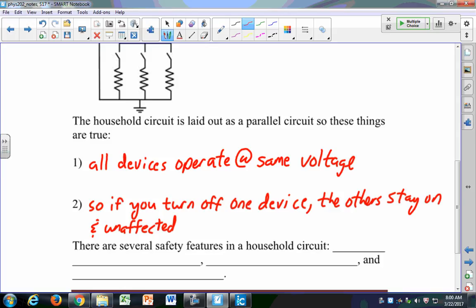It's sort of hard to think about why these are in parallel, but look, I brought a piece of wire. This came from our house. And so it has 3 wires inside of it. I'm going to pass it around. But just forget about the bare wire for now. We'll talk about what that's for. But this is our hot wire, the black, and then the white wire is the neutral wire. The same ones that come in, they're connected to those wires that are coming in off the street. The plus 120 and the neutral wire, which has no voltage at all.